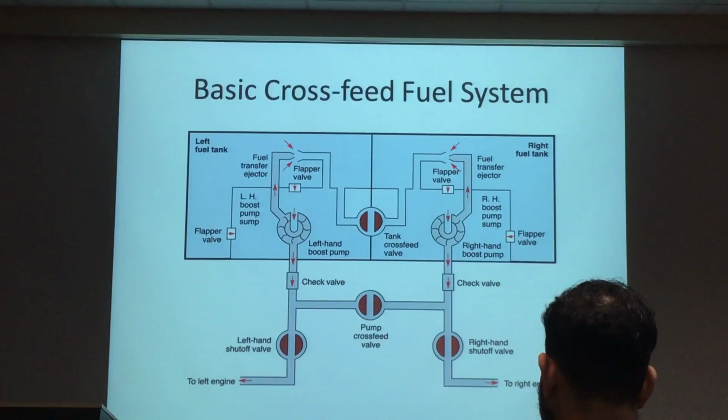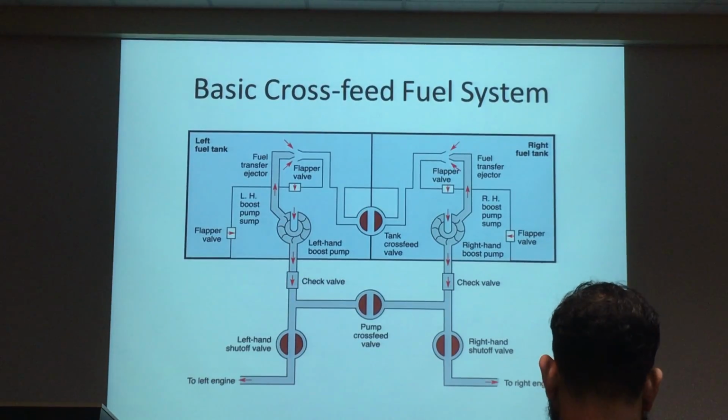Yeah? When it becomes dead weight, and this fuel here, if you keep on using, your aircraft becomes unbalanced. For a small aircraft, not much effect, but for a big jumbo, okay? The imbalance here can become 10 times, 20 times different. So it is too much for the aircraft. What I call trim balance, too much for that. So you need to do another way, you need to transfer, tank to tank transfer.